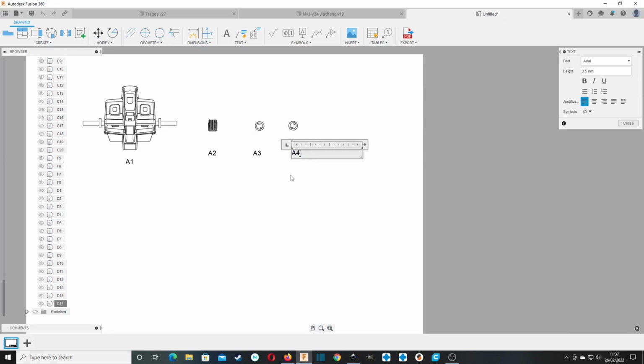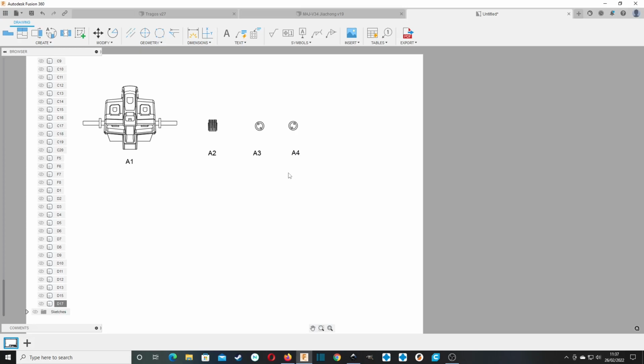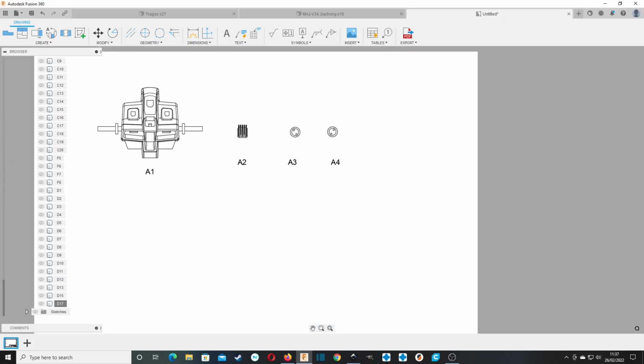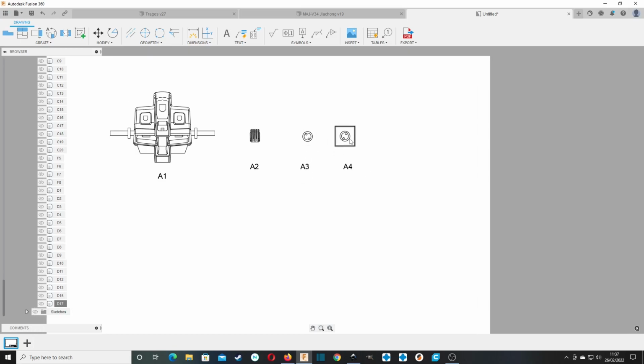And that's another thing when you're making kit. Try to key objects that are left and right handed so they will not fit in the other handed. If you get that wrong, then someone's going to put in a model the wrong way around, and we're going to be not able to actually work on it. So anyway, yeah, this is important because these are very similar parts.